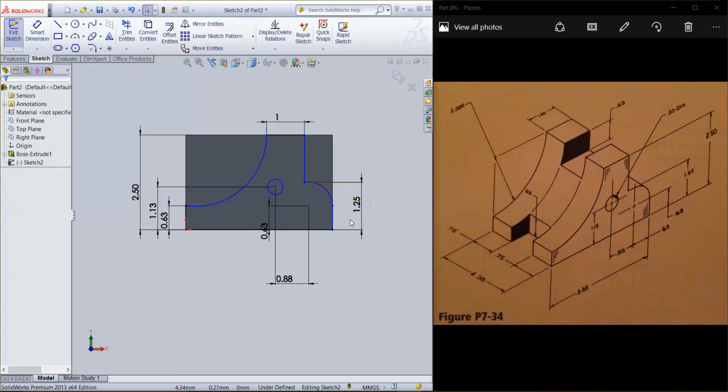Once you reach this point, what you want to do is select all the lines along the periphery and convert them to entities. So now everything is closed. If you look, this is a separate area, this is a separate area, this is a separate area, and this is a separate area. And the reason you want to do that is because it's going to help you when you want to subtract chunks of the part.